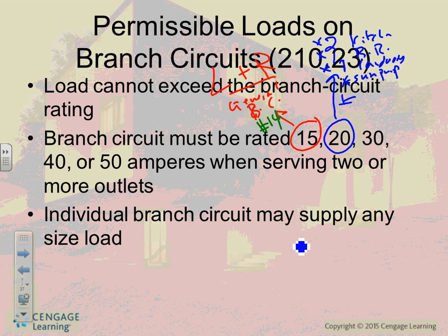What wire size do you use? Quick? 12. Thank you. All right, so let's go to the 30 amp. Where would you use this one? AC. Thank you. What else? Dryer. Dwelling. So these are the 2 places. What size wire do we use, gentlemen? 10. Thank you. 10. Okay.